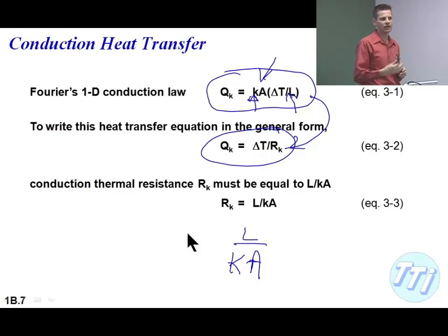So why do we see heat sinks in computers made out of aluminum? Property of the aluminum. Yes, it's thermal conductivity. It's a good mover of heat. If you made it out of styrofoam, it probably wouldn't work very well. And that's because styrofoam has actually a very low thermal conductivity, and so the K value is very low for that. So playing around with those parameters, you can change thermal resistance. And so this is a very simplistic equation that you can use for just doing a simple assessment.